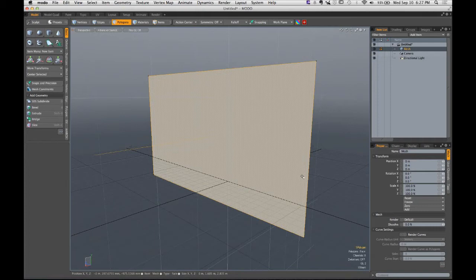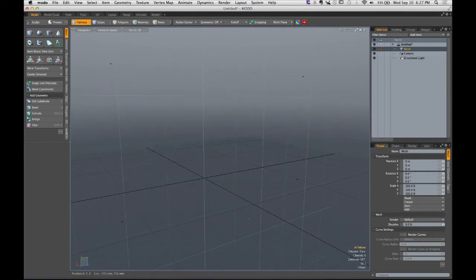When our perspective, or the render camera's perspective, is within a certain angle of this surface normal, we're going to see that shape, right? We're going to see that polygon. But the moment that angle changes, so when the surface normal is facing the opposite direction of our view, what's going to happen? We're not going to see anything. It's going to become invisible, okay? The backs of all of our polygons are invisible. The only thing that we're ever going to see are the fronts of our polygons, which is why the back is invisible, okay?